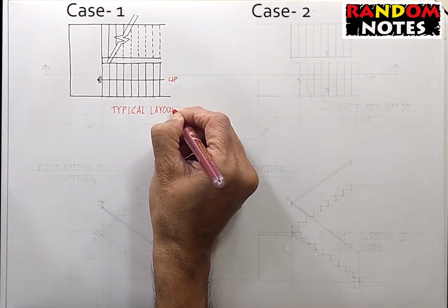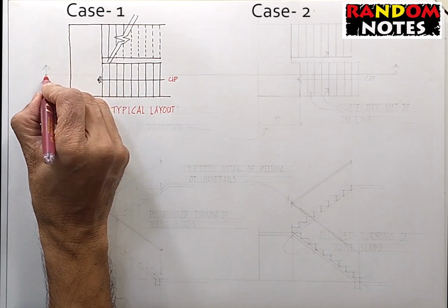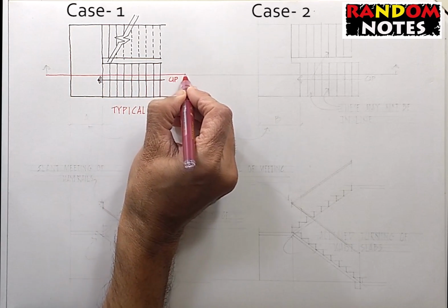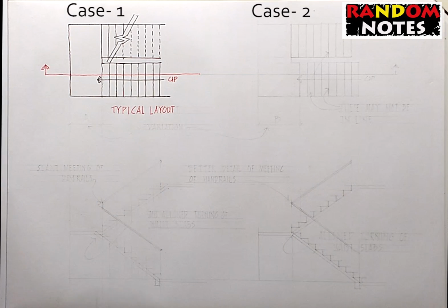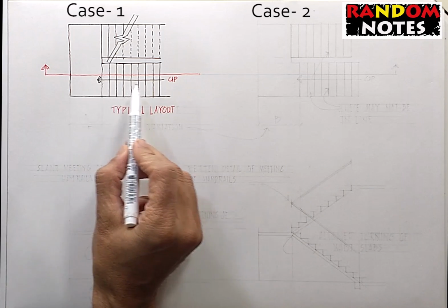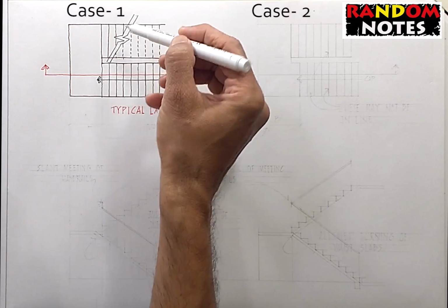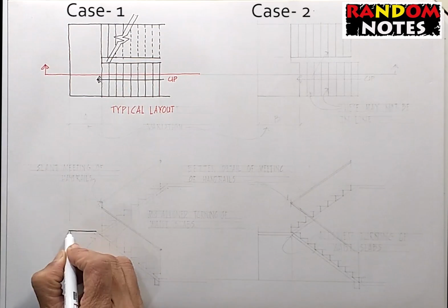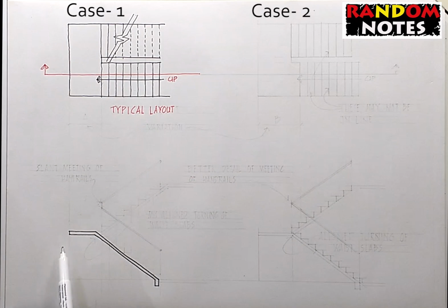Let us now derive the section of the staircase from the plan that we drafted and see how it affects the parts of the staircase. A section plane generally cuts through the first flight rising from a staircase, with the other flight visible in the elevation behind it. Thus we will see this flight in front in section with an RCC waist slab and brick steps on that. Beyond this, we see the elevation of the flight rising from the mid landing. For our understanding, we will make its waist slab and the brick steps also. This is the waist slab which is coming down and meeting the plinth beam below.